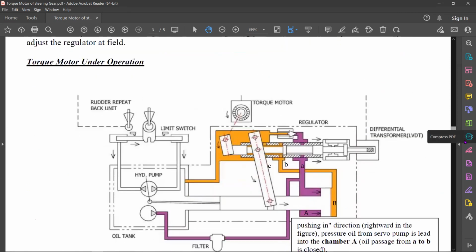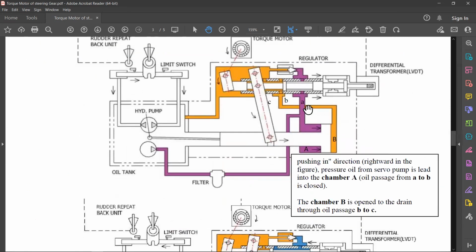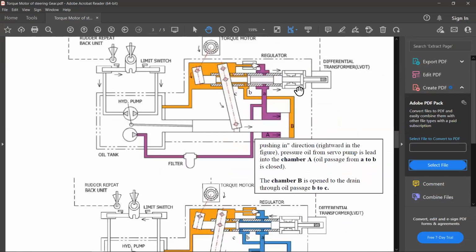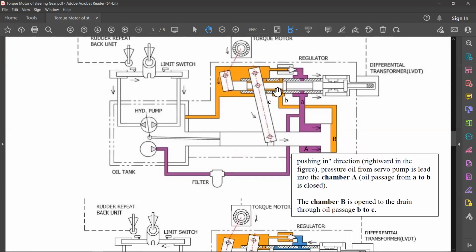Yes, yes. Because see, this thing might be something new because in the textbooks you do not have this entire thing. You might have just a mention even in your manuals that torque motor is there, but ये कैसे काम करता है is important. Because see, there is a DC motor, and DC motor controls the spool valve, and as the spool moves, proportionately this piston moves. Okay, both of them operate together. That means as the spool moves, simultaneously this piston will move. Not that one effect follows the other.